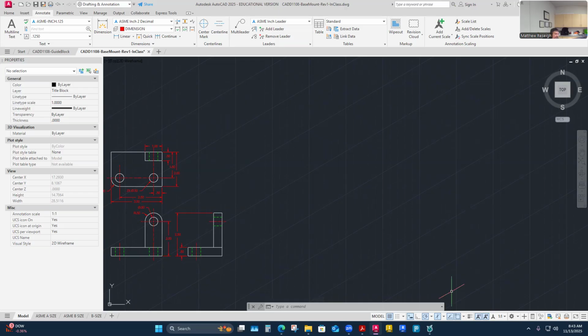It's really critical that you're on the right plane when you're applying a circle that's going to become an ellipse. You have to place that on the right iso plane. Otherwise, you won't be able to place that circle correctly. It's going to associate it with the plane that you've got selected here. But that's about it. Otherwise, lines and stuff, you can draw them on any plane, whichever one helps you visualize 3D a little bit better. So my default a lot is just to have my iso plane left on here.